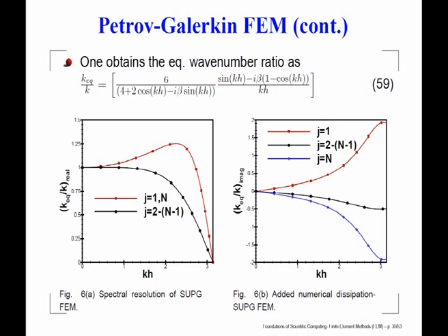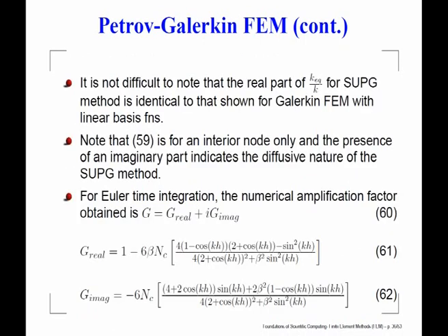So, that should remind you that when we were talking about the error propagation equation, I compared all 4 methods. I compared a CD2 method with a compact scheme, then this SUPG method, and the method that is used in Fluent, that is QUICK. And what we found, of course, is that Fluent and SUPG actually remove the signal, and that was the reason because of this.